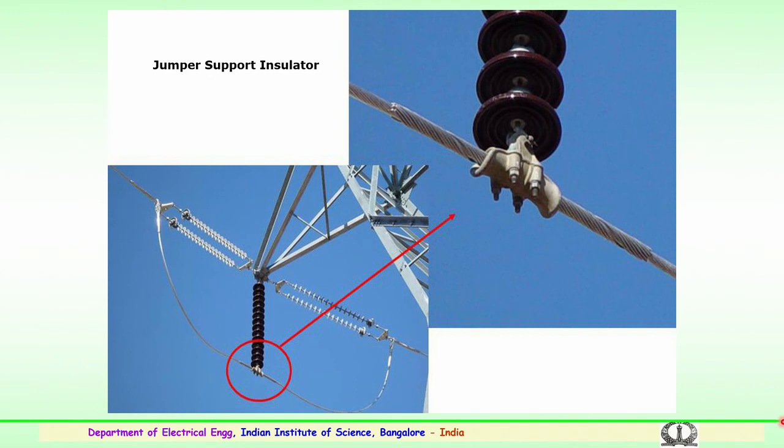So, apart from the armor rods, this is for a single conductor to suppress the oscillations. Further, a twin conductor, 4 or 8 conductor will have a damper arrangement. Usually for a single conductor near the insulator string, armor rods are fixed to provide damping of oscillations. Further, in that area if oscillations are seen, the dampers could also be used.